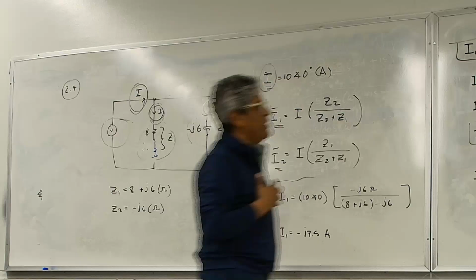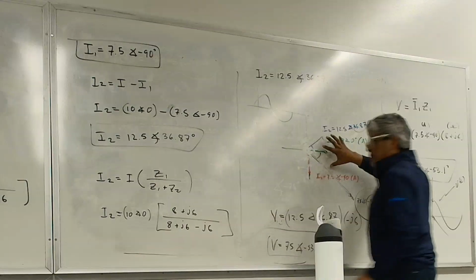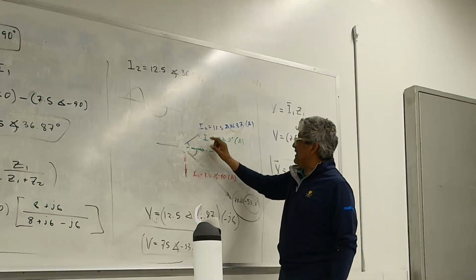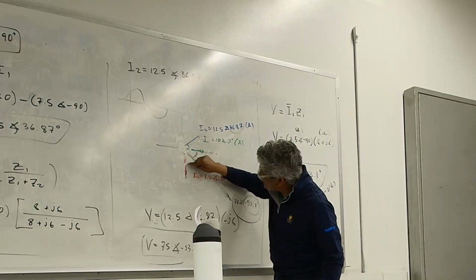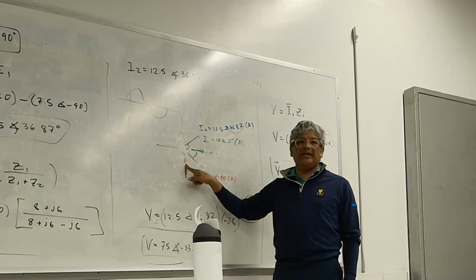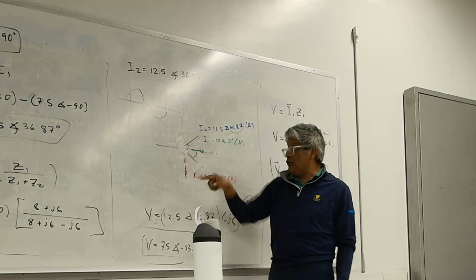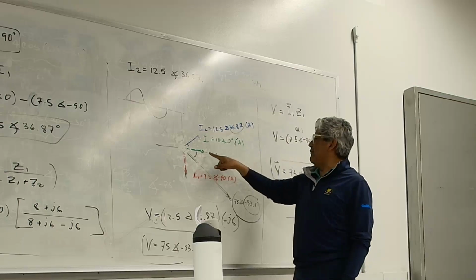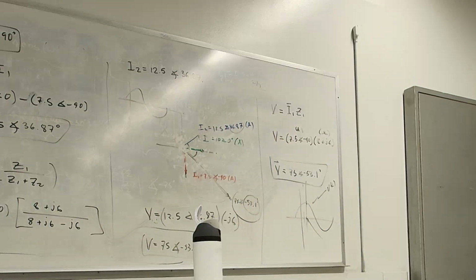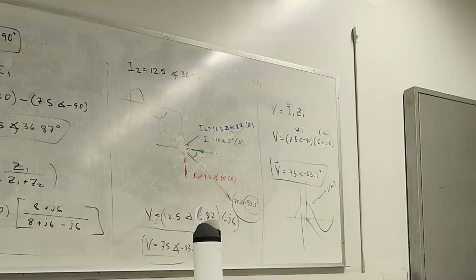I won't get this deep into this whole theory once you do it, but what I want to make sure is really that you get a grasp for the relationship between phasors. I don't want you to focus too much on the angle that you're measuring. I want you to focus on the angle between them, because the angle between them is what's telling you. So if you did all this, and you ended up with the current flowing through this inductor lagging in comparison to this voltage, then you know you did something wrong.